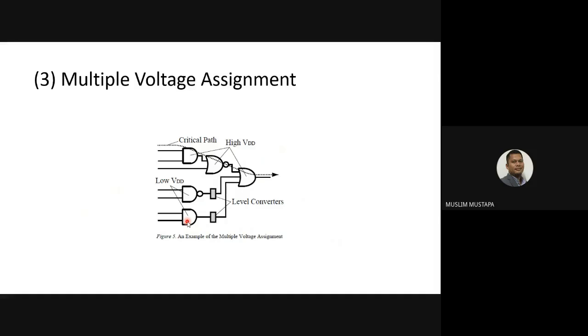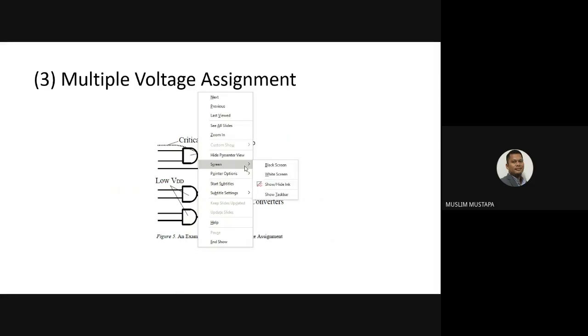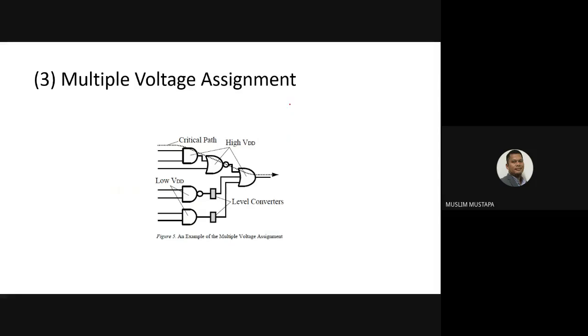That's why if you look into the data sheet, normally they're going to give you a range for the devices to operate. For example, for the circuit to read a 1, what voltage do they need to receive? For example, 3.3 volt until 5 volt, so you can see the range. For a high signal the voltage threshold might be 3.3 to 5 volt, and for zero maybe it's 0 to 0.2 volt.